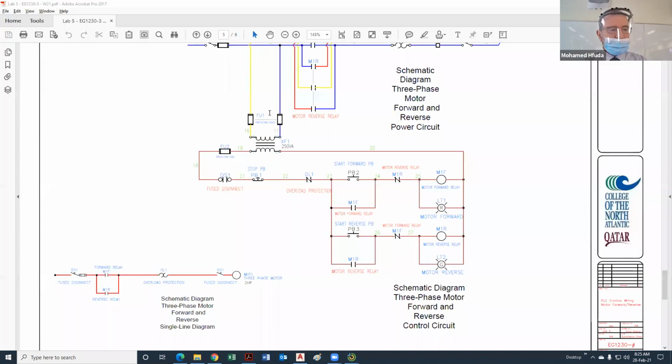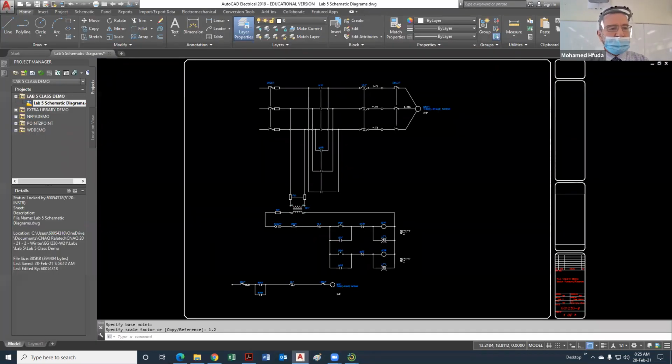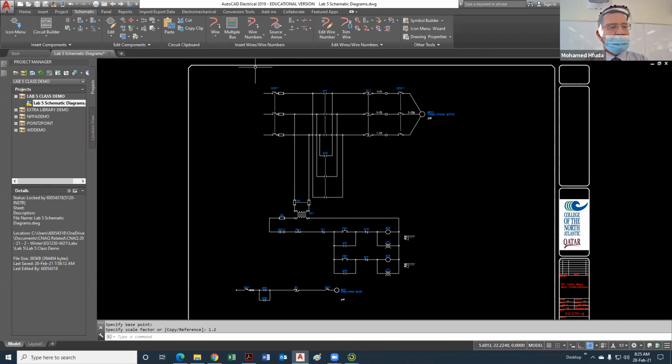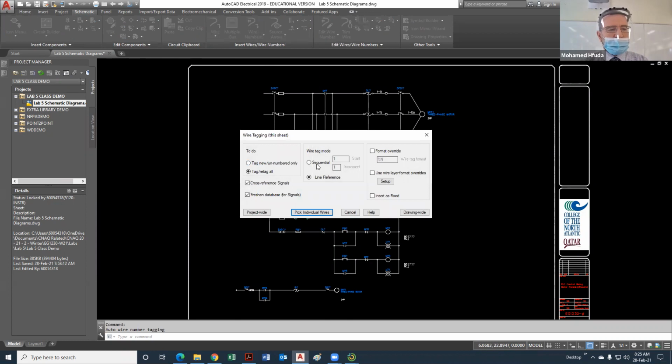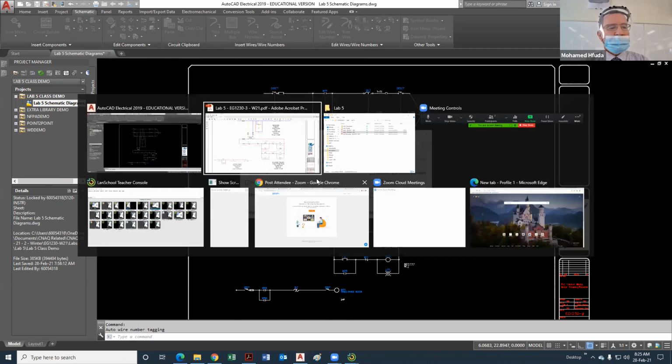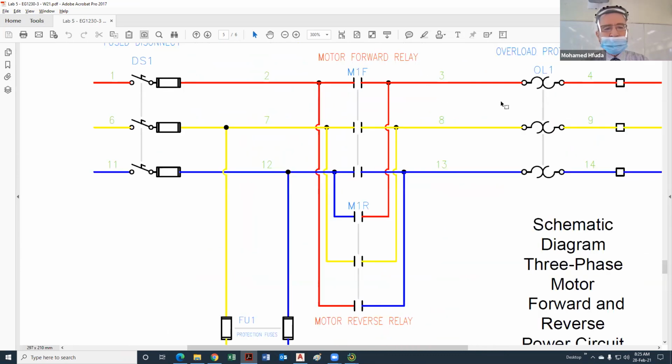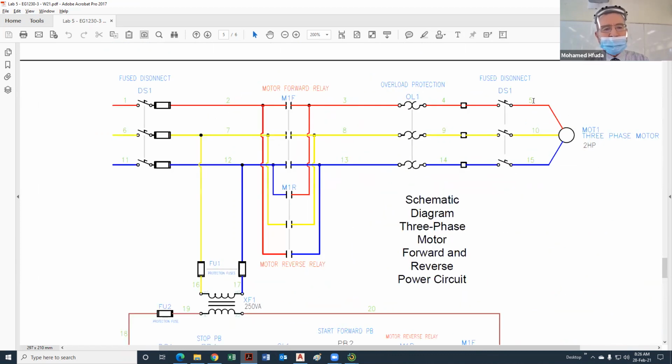Okay, so as far as the line types and wire colors and so on, I'll leave you to that, and you can ask if you have any problems setting it. But what I want to show you now, which we didn't do before, is wire numbers. Wire numbers on the schematic. We're going to do wire numbers sequential, because you can see here the wire numbers. See these? 1, 2, 3, 4, 5, 6, 7, 8, and so on. Here's the 5.